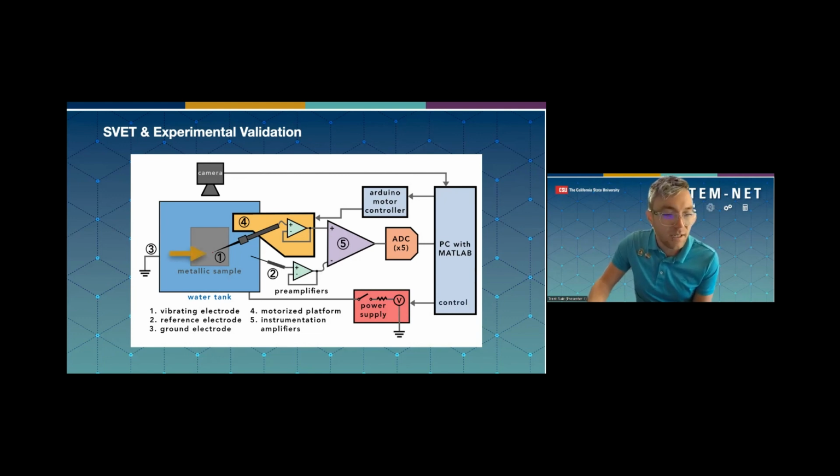In this diagram, we see the vibrating probe, which is connected to the solenoid or the transducer, depending on which experiment we're running. We have cameras to aid in visual inspection. Current density maps look quite a bit different, especially in the early stages of corrosion, than the object that is perceived by our eyes. I took a broken down 3D printer, it was actually 4, parted them together and removed the extruder, which has now become our XYZ plotter for the probe.